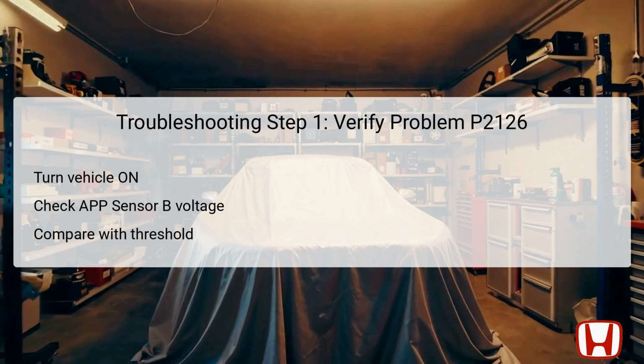If the voltage matches these thresholds, you are confirming the fault, leading you to proceed with further diagnostic steps. If no match is found, it indicates the system may currently be operating without faults. Thus, further investigation into wiring connections is needed.